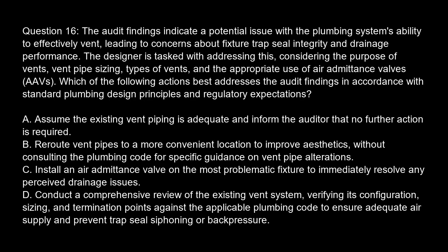Question 16. The audit findings indicate a potential issue with the plumbing system's ability to effectively vent, leading to concerns about fixture trap seal integrity and drainage performance. The designer is tasked with addressing this, considering the purpose of vents, vent pipe sizing, types of vents, and the appropriate use of air admittance valves, AAV. Which of the following actions best addresses the audit findings in accordance with standard plumbing design principles and regulatory expectations?